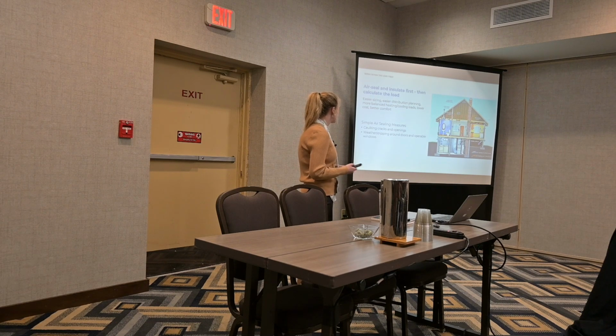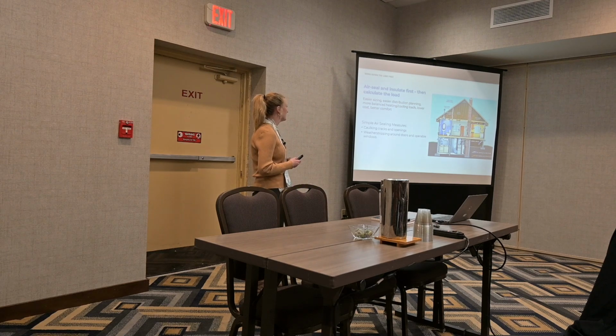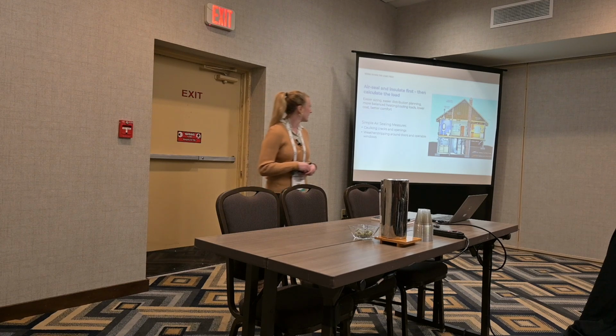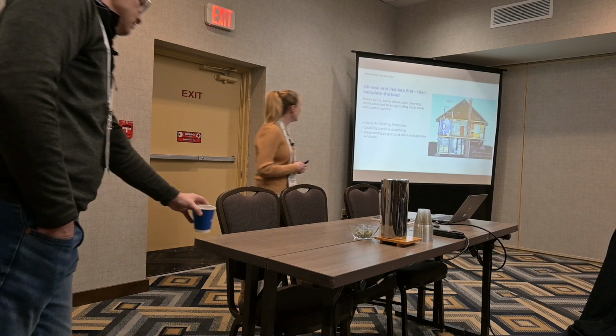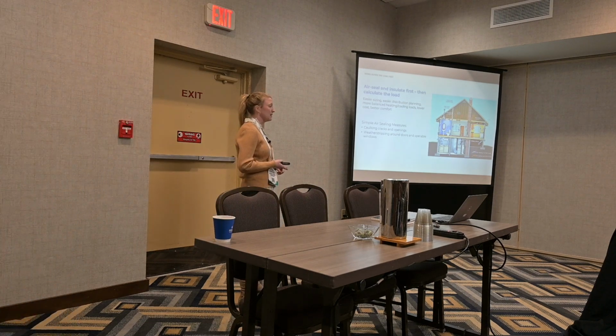Most contractors should be able to do simple air sealing measures like caulking and weather stripping, but you really want to partner with a home performance contractor to really get that load down, or add that portion to your business if you can. Once you're reducing the load, it leads to easier sizing when it comes to the heat pump, easier distribution planning, more balanced heating and cooling loads, lower cost, and better comfort.